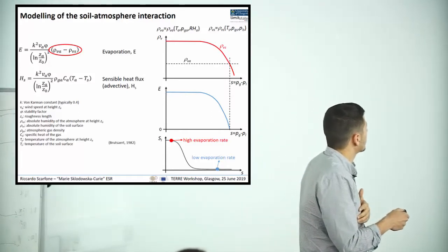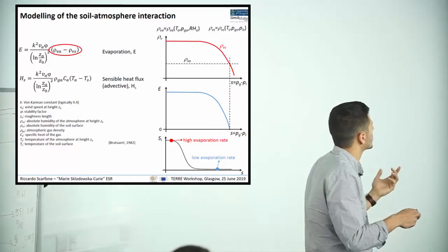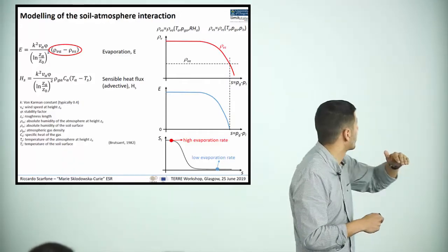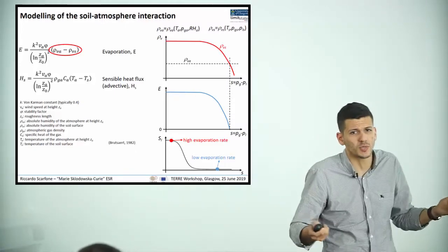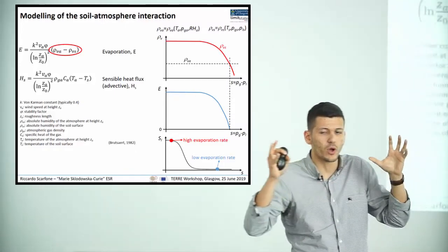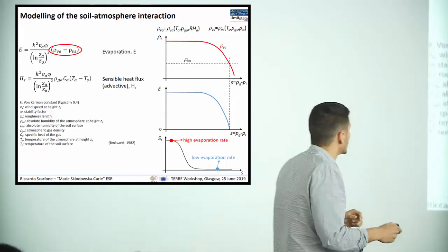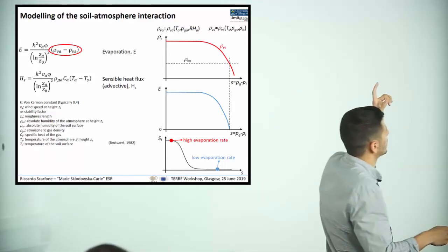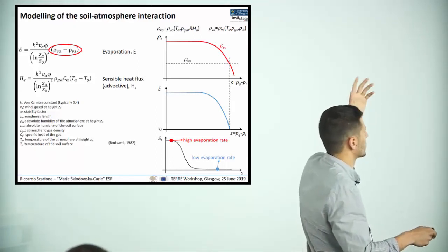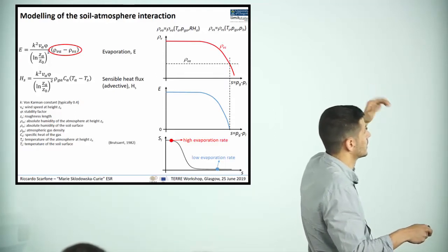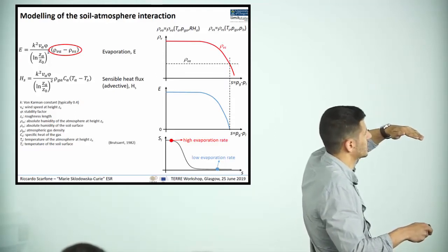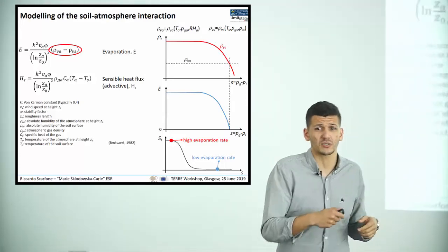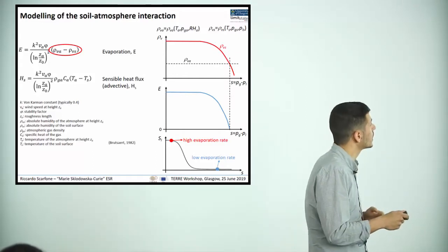For the evaporation, another driving force is the difference between the absolute humidity of the atmosphere and the absolute humidity at the soil surface, where the absolute humidity is the mass of vapor over a unit volume of moist air. The atmospheric one is a function of atmospheric temperature, gas pressure, and relative humidity. At the soil surface, it is a function of temperature, gas pressure, and liquid pressure, which is in particular governed by the psychrometric law.